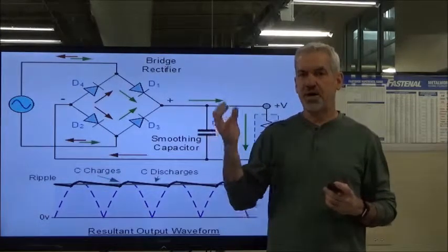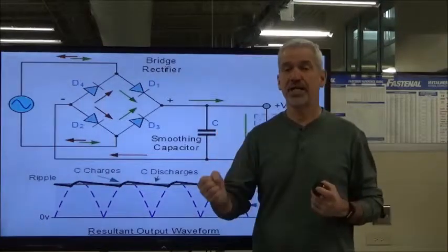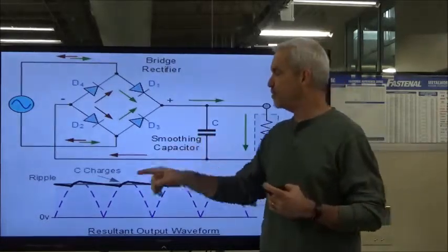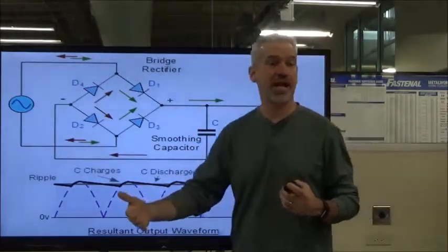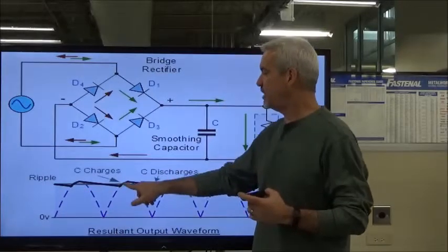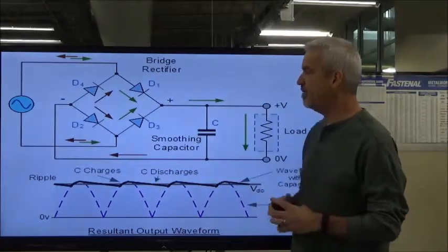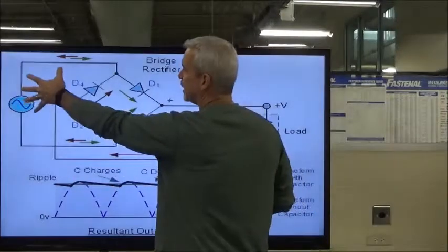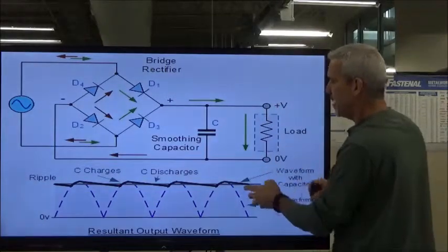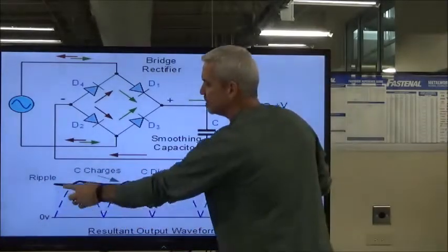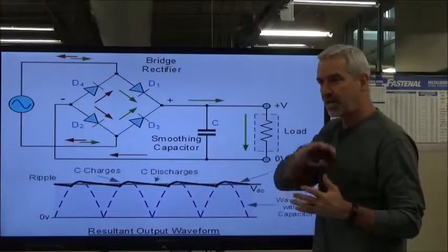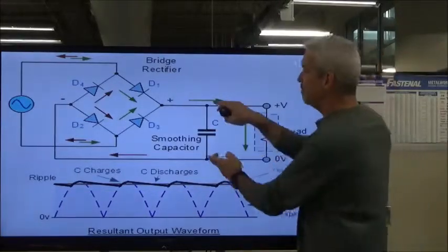And whenever the voltage drops and it needs to give it sort of like a booster shot, it will release voltage based on how much is needed, okay? And it will help smooth out the ripple, okay? In other words, it takes up the slack. That's a good way to look at it there. It takes up the slack of when these dips in our DC ripple start to take effect, okay? So we've already talked about how we're taking the AC, going through the rectifier, and we're coming out with our DC, and our load right here is experiencing this up and down. Still all positive voltage like a DC signal, but it's got a lot of ripple and it's not clean. So we've got to clean it up with this capacitor.